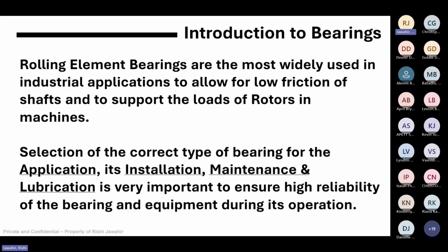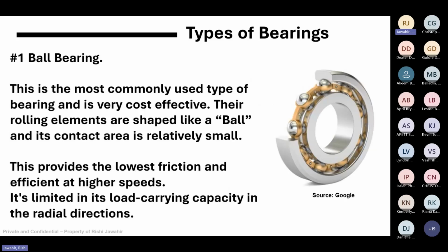Also, in the maintenance and lubrication, we may have the wrong maintenance strategy. We may be using the wrong type of lubricant or the wrong lubrication schedule, and that also affects the reliability and operation of our bearings, right?